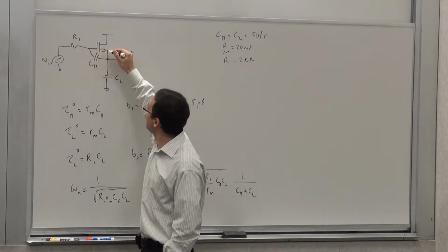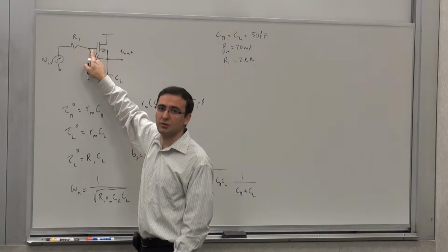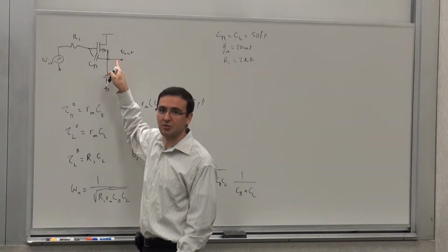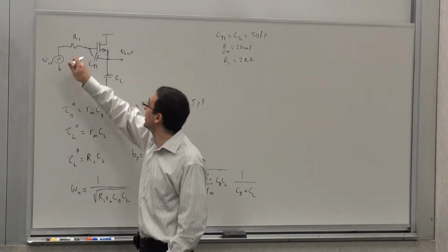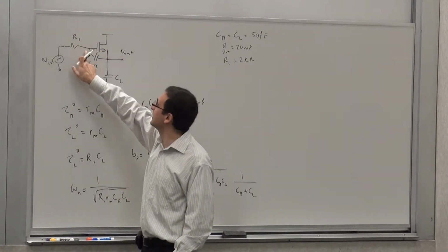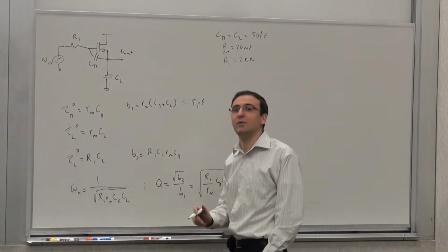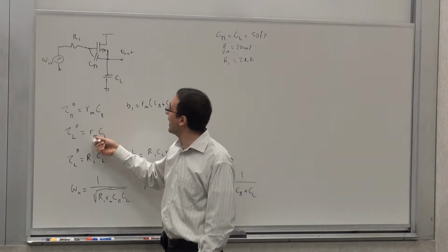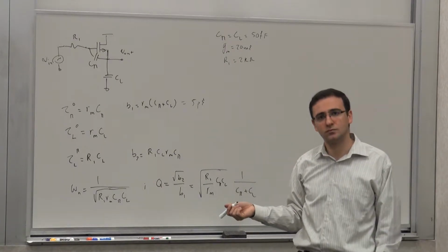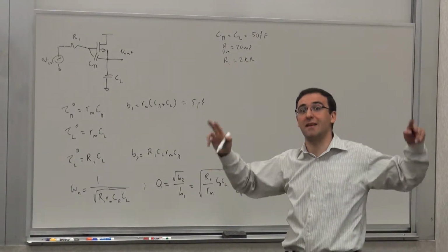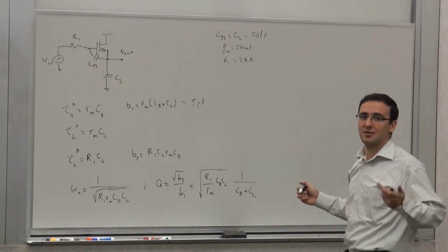Right. So what happens is that this is a MOSFET. You can think about the reflection rule. If you reflect it, this becomes divided by infinity, so it becomes 0. Another way of thinking is that this voltage and this voltage are the same, because there's no current flowing at DC. So this is like ground, so it would be just Rm. If it were bipolar, then this would be Rm plus R1 divided by beta, or 1 plus beta. But in this case, since beta is infinity, it basically gets divided by infinity.